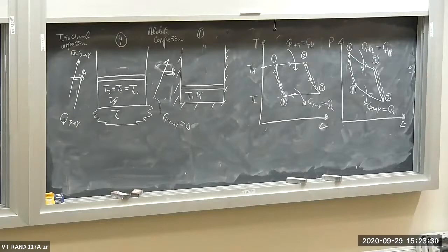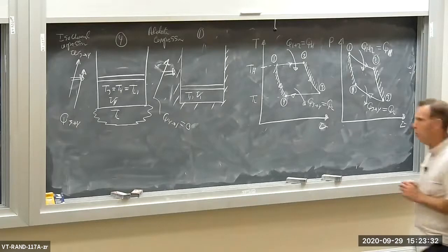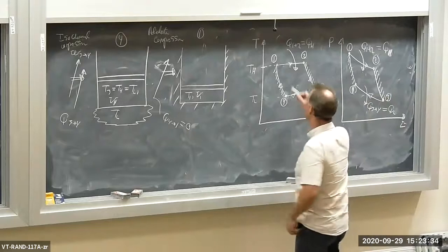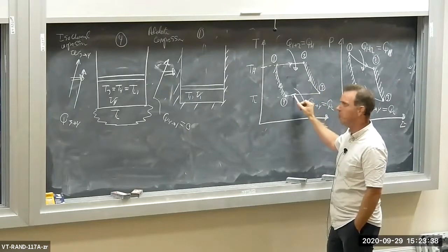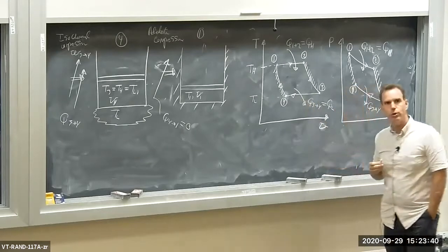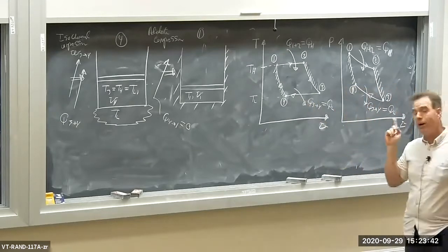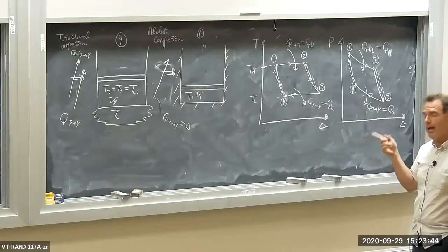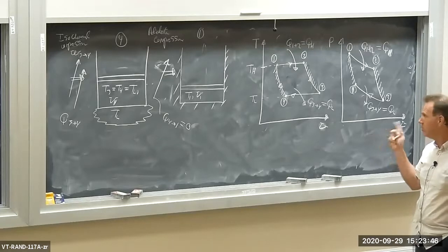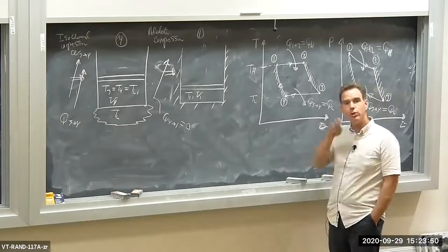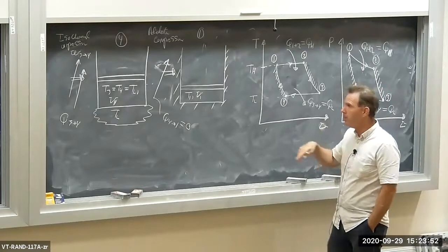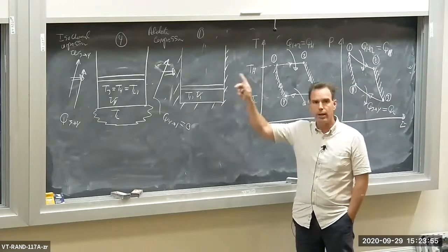You might ask yourself, well, what about heat transfer? Remember, the heat transfer occurs when the system temperature is equal to TH or TL. So there's no temperature difference between the gas or the working fluid and the reservoirs. So the heat transfer occurs at the reservoir temperatures, and there's no delta T between the working fluid and the reservoirs.